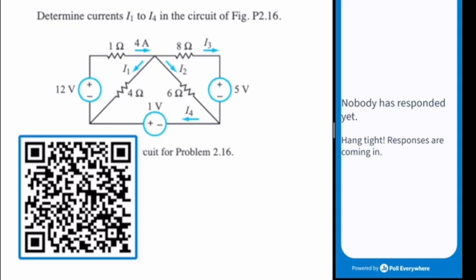Because you have a parallel branch to the parallel, the resistance across that from the left to the right is going to be, you don't know what it is. You're correct on this one, it's not valid to say that the equivalent resistance between here and there by 1 is going to be 10 ohms. It actually won't.